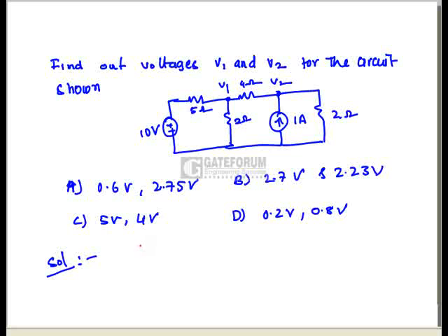If you see the circuit, here this is V1, and according to nodal analysis, all outgoing currents at any node equal 0. If I say outgoing currents, that means our node voltage must be greater than another node voltage. That we have to assume. Then only we say that the current is outgoing from that branch. So here if you observe node 1, how many branches are there? 1, 2, 3. 3 branches are intersecting here, and if you observe node 2 also, 3 branches are intersecting.